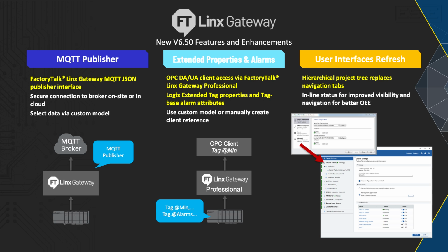When you choose one over the other, it just depends on what you're doing and what you currently have in your plant. I'd say FactoryTalk Link's Gateway is geared towards a site that already has a lot of FactoryTalk Link data servers, because it's really meant to get that data and send it out beyond where it is. If you don't have that, then Optics is a good fit, because it already has native drivers for PLCs other than Rockwell.